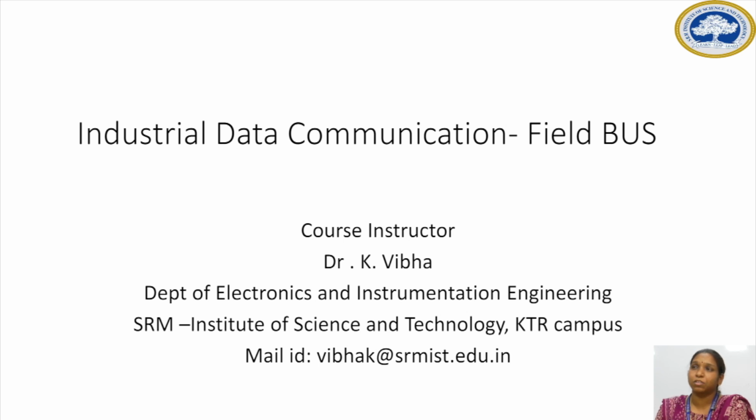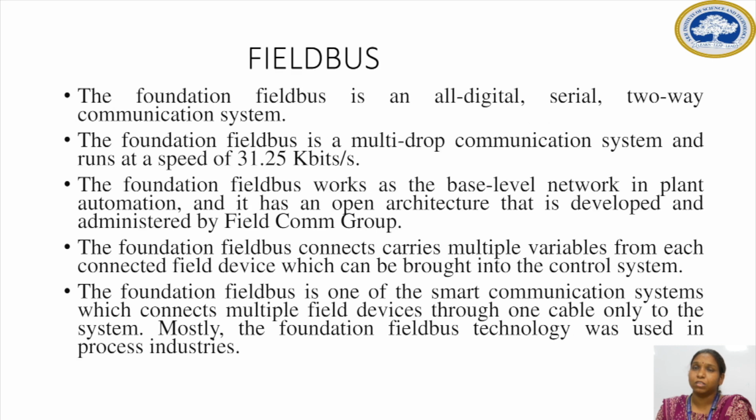Good day to all. Today we are going to see about field bus, which comes under the subject title Industrial Data Communication. What is field bus? The foundation field bus is an all digital serial two-way communication system. It is a multi-drop communication system and runs at a speed of 31.25 kilobits per second.